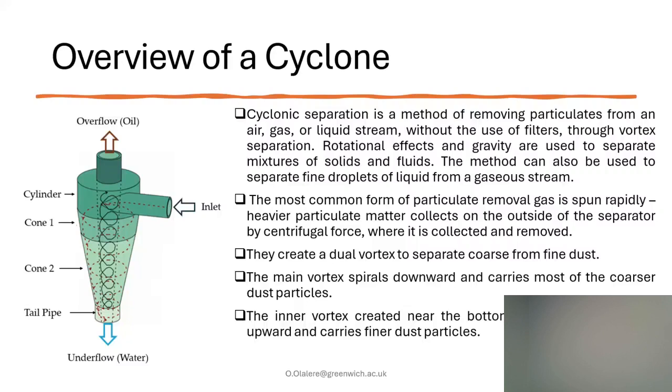So the force up will be different from the force down. Right? So now, the most common form of particulate: the heavier particle is collected on the outside of the separator by centrifugal force, where it is collected and removed.